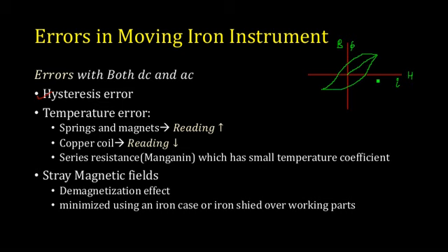Now what happens is that if you are considering the case of an AC, you will be following this outer path. Once it is magnetized, you will be following the outer path once for every cycle. So for 50 cycles we will be following this path for magnetization as well as demagnetization of your magnetic field. During the positive half cycle it will be increasing like this, then reaches the peak and then it reduces. And when the current reaches 0, your flux density will be reversing and it will have a negative value when you move this way. So you'll have such a variation.